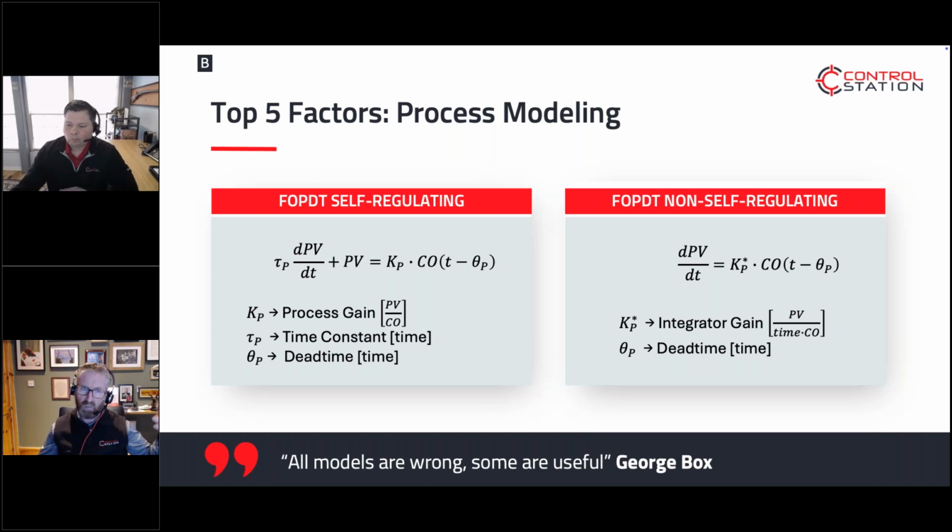You know, that delta, the PV over output, it's that relationship, the time constant. If this process takes 3 minutes or 3 hours to change, that's going to feed into how you're going to control it. And the dead time is dead time. It's a very tough one to change if it's bad. It's going to be a value that you're going to have to work with, or you're going to have to do a major design change, which doesn't happen.